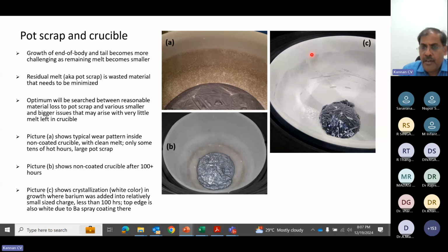After melting, the molten silicon level has come down to even 1/3 or 3/4 of the crucible height, and when you start pulling, the level goes down further. Finally, this area, where the molten silicon is in contact with the quartz crucible for a longer period, has its coating deteriorated. So once you cool down, you cannot use this crucible again. It's a one-time use.